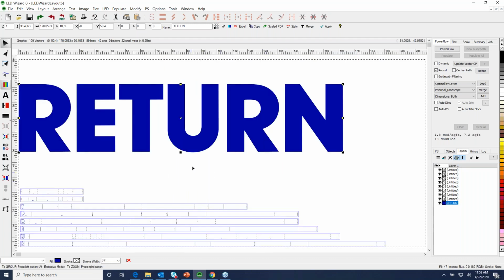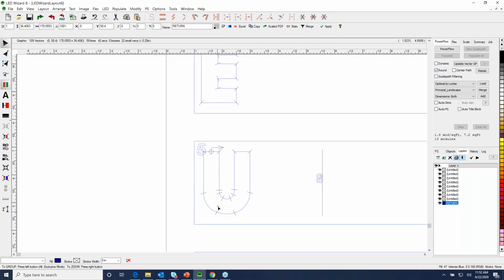One thing that is important here, similar to exporting to an automatic bending machine, is you do want this artwork to be clean. I've seen some of these patterns where someone didn't clean this up, and there's a million points along these arcs, and it becomes not very useful. In that case, some customers will prioritize the hard bends first as the most critical, and use the softer bends as a guideline.